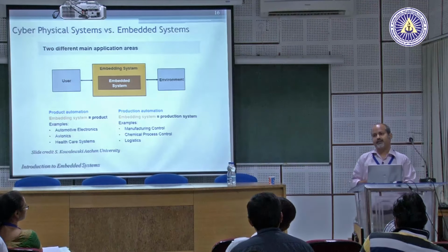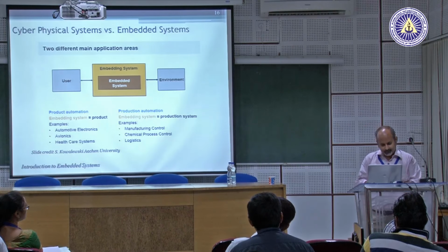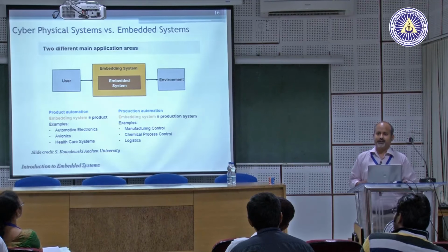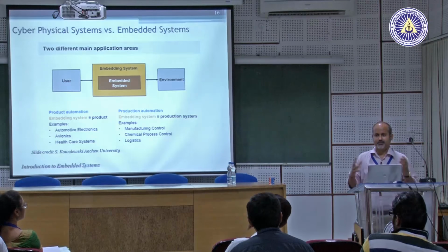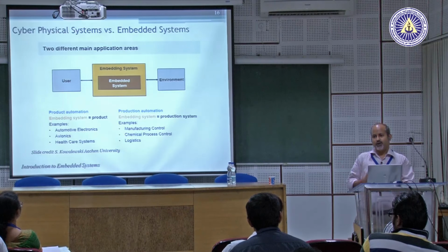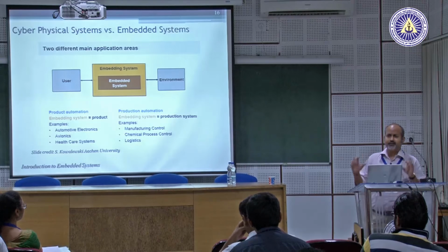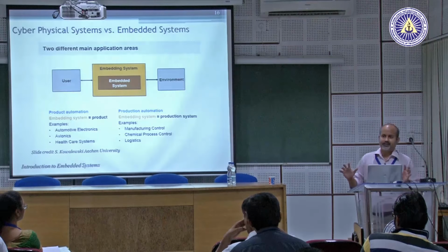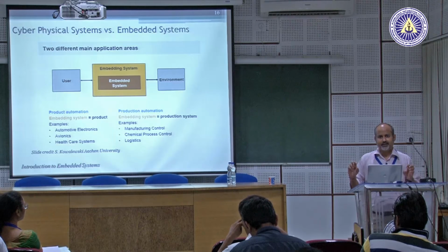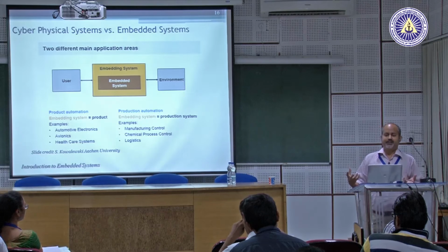In 2003, a similar thing happened in New York, and all of these things happen because the stability of the control trajectory of this entire large system, a geographically distributed physical system, was out of the stable trajectory, and it collapsed. So in order to keep this entire system in trajectory, you have to apply control, and you have to apply control by knowing the current state of the system. So state estimation is what is done by all the control centers.